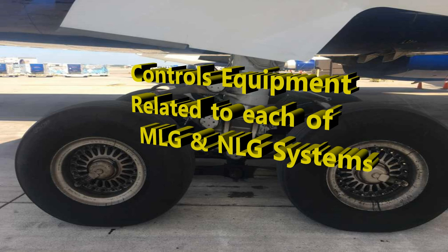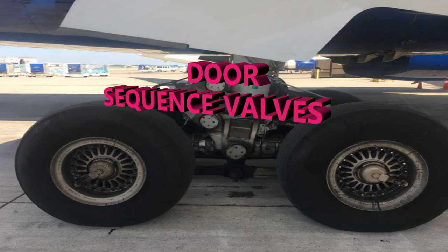Okay, the manifold assemblies are actually integrated with their valves, and they're used to control the normal system of operating the landing gears. You also have some door sequence valves that send the hydraulic fluid to the open or the closed side of the door actuators. The gear sequence valves are going to send that fluid in order to either extend or retract, right? That's what it's there for.